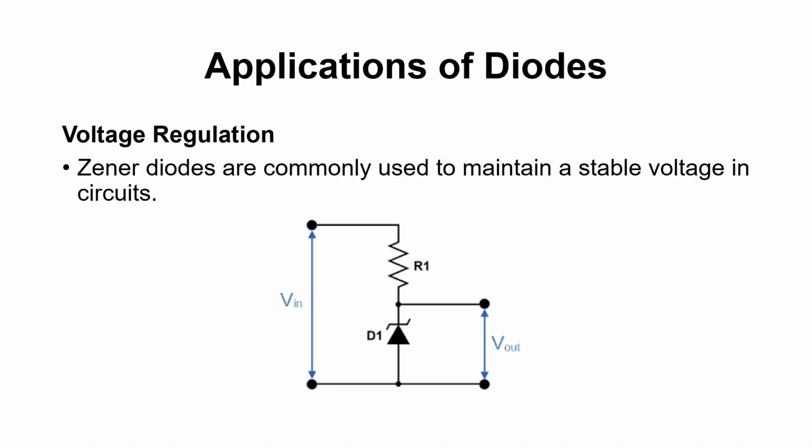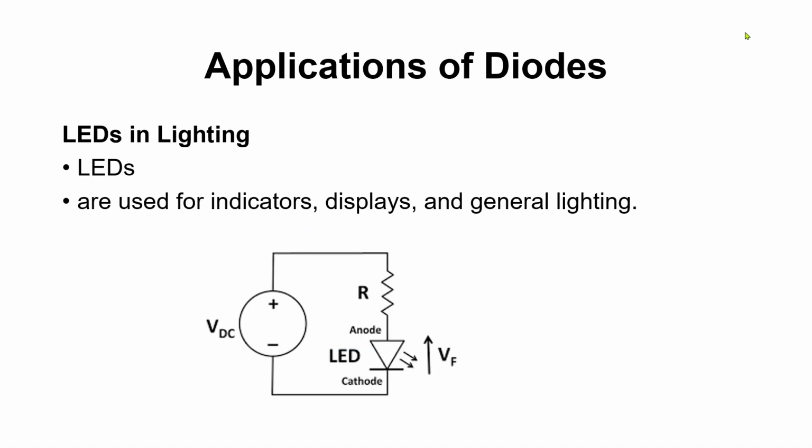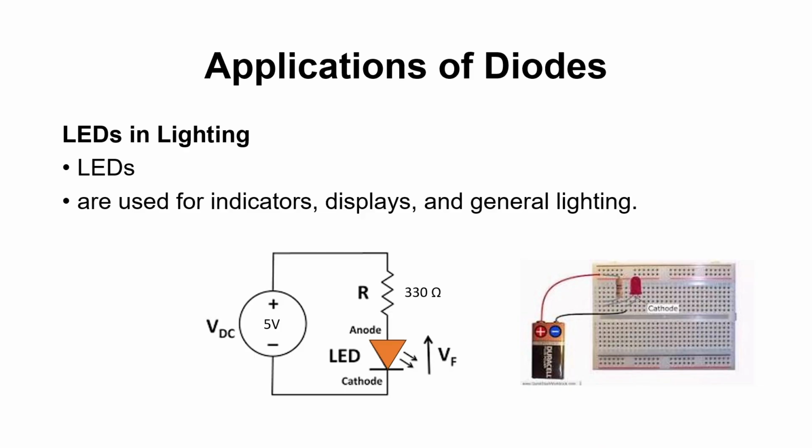And finally, a super simple one almost everyone starts with. Lighting an LED safely. Just put a current limiting resistor in series with the LED and your power source, like 5 volts. For a typical LED, a 330 ohm resistor works nicely with 5 volts. Without the resistor, poof, the LED dies quickly. Here are a couple of easy breadboard examples.